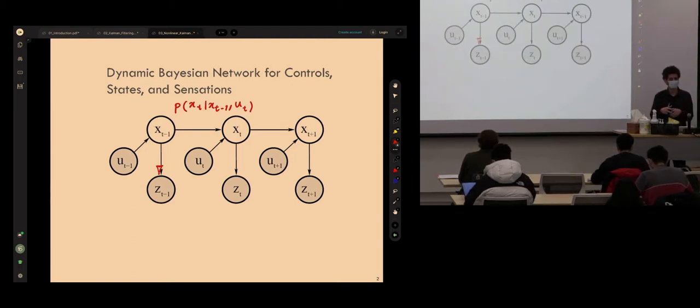But because there is no perfect actuator in the real world, and there are so many factors, for example the carpet, or maybe there's a bump, as the robot is moving with wheels, it won't be perfectly at the place that your model tells you. So necessarily, you will deal with some noise or a region of possible locations where the robot can end up, and that motivates the probabilistic model. The noise is supposed to capture that region that we hypothesize the robot will be in. So that's the probabilistic motion model.